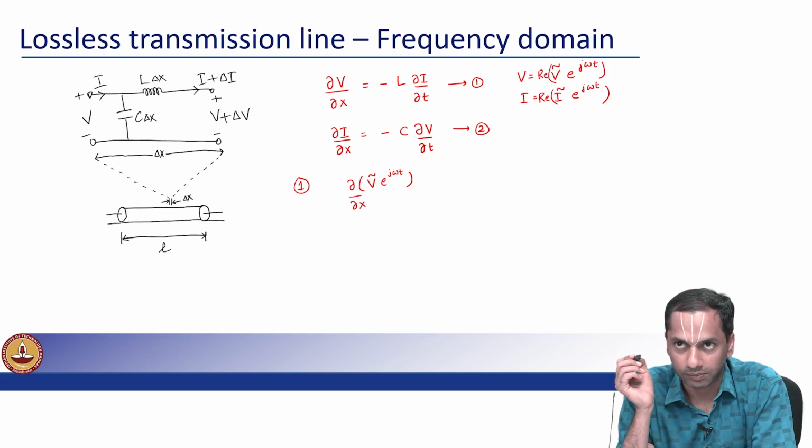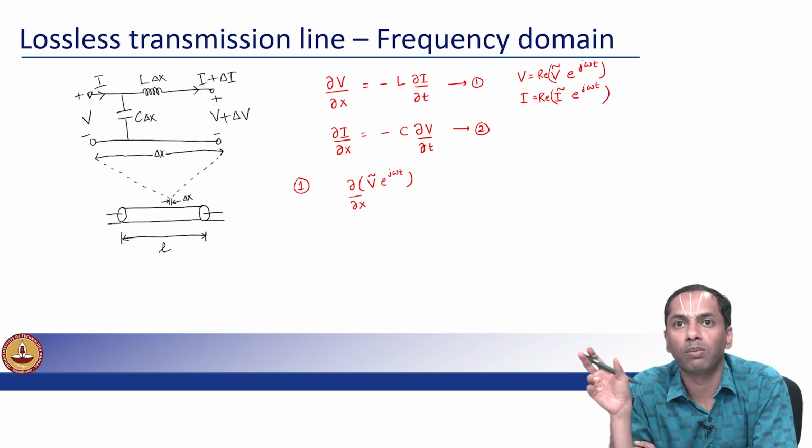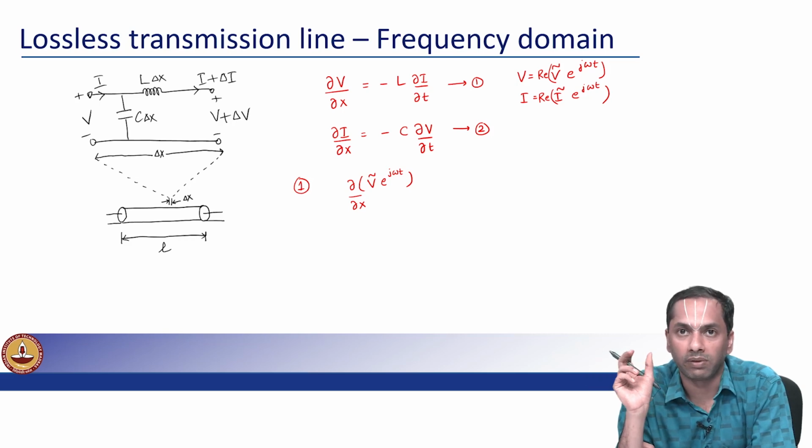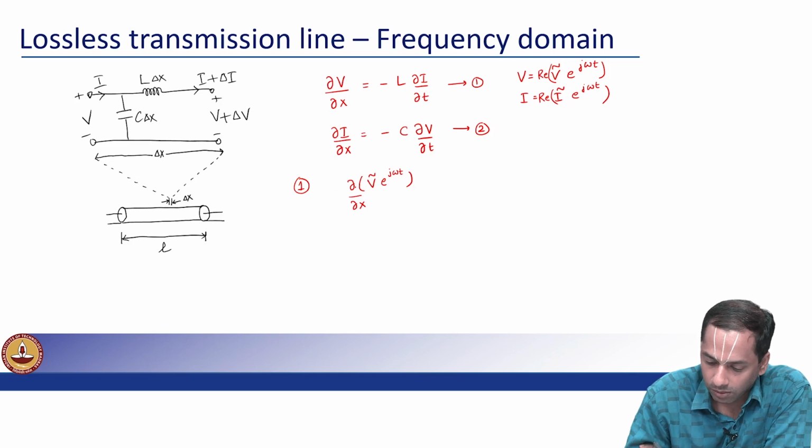We are just saying that we are representing the cosine as the real part of e^{jωt}, and the reason to use exponentials is that when we do derivatives or integrals on these functions, we simply get back the same e^{jωt} only multiplied by a prefactor, right? So the real part, I can take it out.